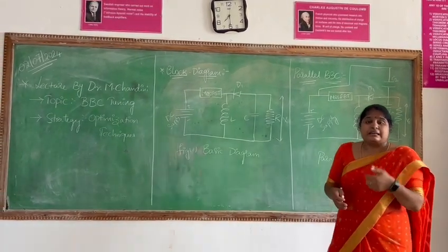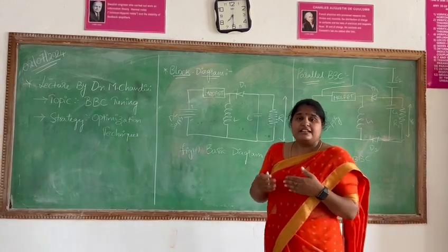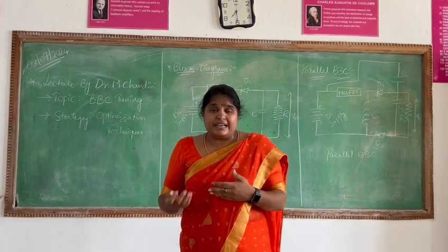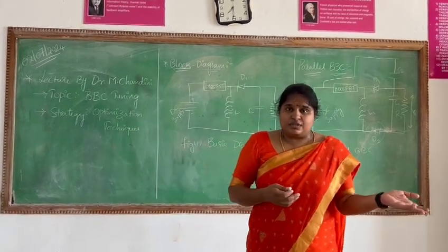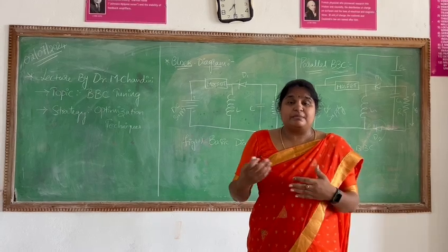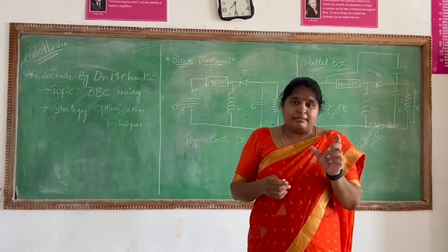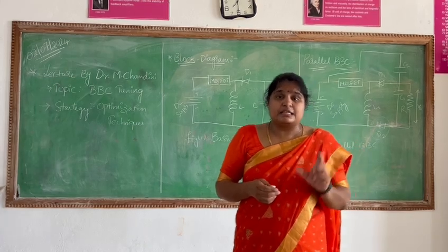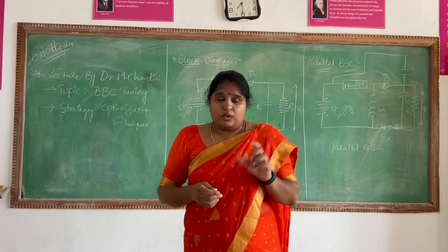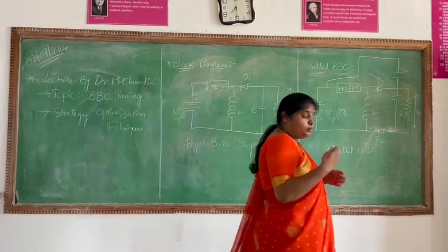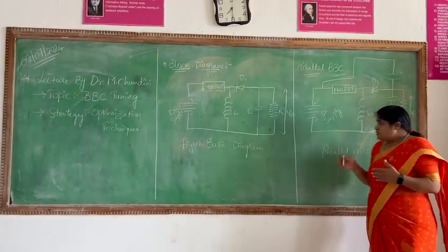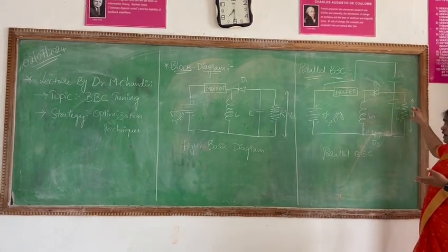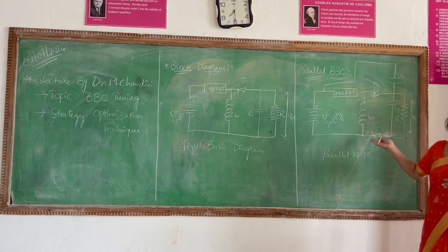What do you mean by ripples? Ripples are nothing but, whenever there is MOSFET switching, some voltage goes to values which are not within permissible limits. That is the main basic notion of ripple content. Ripple content is nothing but the disturbances of the voltages, so the output voltage gets disturbed. If we are not getting the voltage accurately, the output cannot be used for any application.